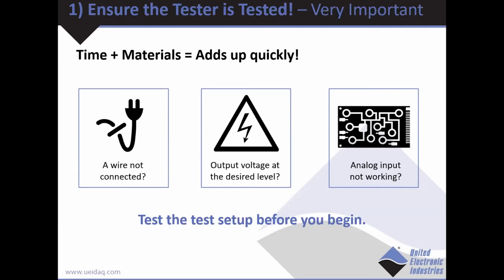But if the load has changed, then you might not see that same voltage. If you're trying to output 6 volts into 1 ohm, you might be shorting your analog output. So we want to try to detect that scenario and measure the output voltage, but we don't want to add extra wiring. We could take an analog input and wire it to that analog output, but again, now we're taking an extra channel and we're adding more cabling.